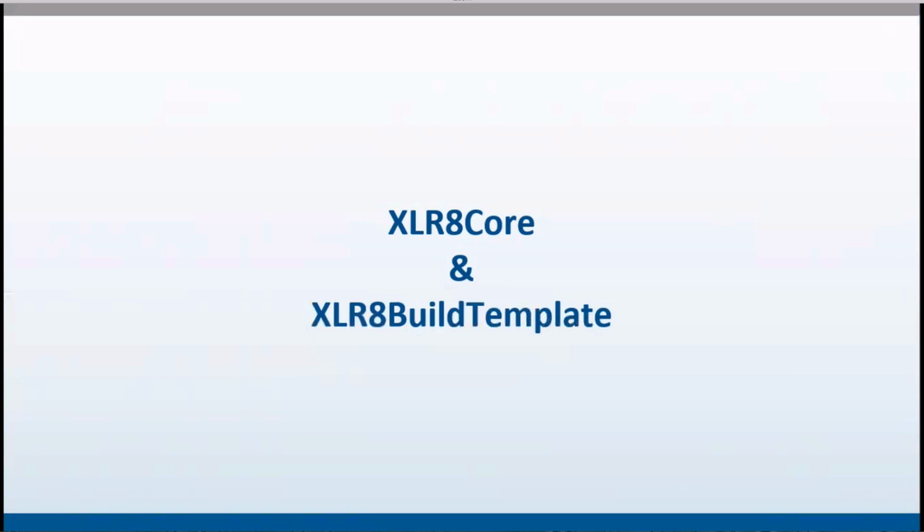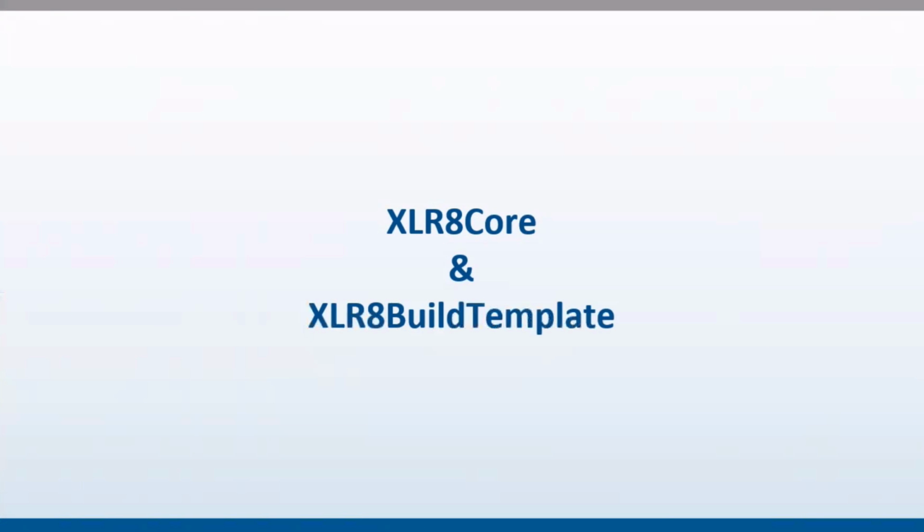There are two core libraries provided for OpenXLR8 that provide the foundation for running the OpenXLR8 flow: XLR8 Core and XLR8 Build Template. The XLR8 Core contains all the base libraries, scripts, and source files that are needed to compile the entire FPGA design in Quartus. The Build Template provides a framework for users to add their own custom logic. It's a template where you modify a few files here and there, and that allows you to bring in your own logic.